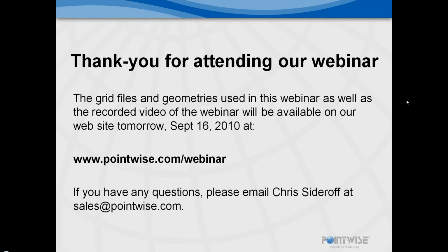Possibly you could use similar techniques to what Chris used to remove the poles at the fillet. You could use them to remove the poles at the leading and trailing edge in the tip region. However, in general, this is a technique that's been used in a lot of cases for tip gap regions to quickly and simply create a grid in this region. And it tends to not cause problems computationally because the area of the pole is 0, so you're not actually calculating any flow in that region.